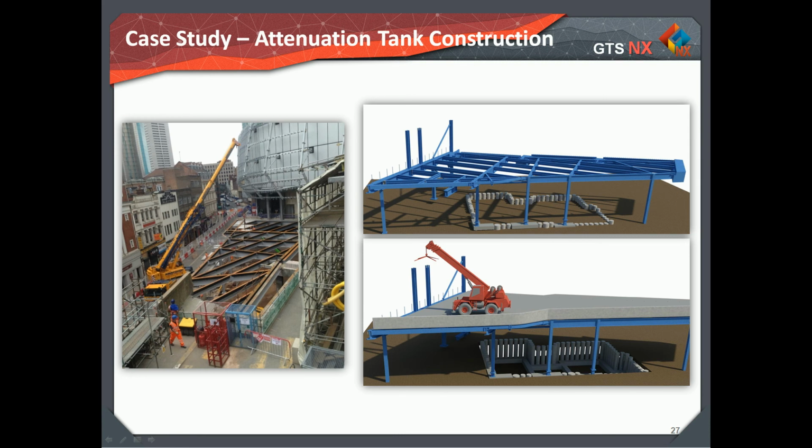The research case study relates to the 4-meter deep excavation works required for the construction of an attenuation tank at Birmingham New Street Station redevelopment project. The attenuation tank was to be formed using contiguous CFA piled walls and with base and roof slabs, which you don't see here but will be shown later. The slabs act as truss in permanent conditions.